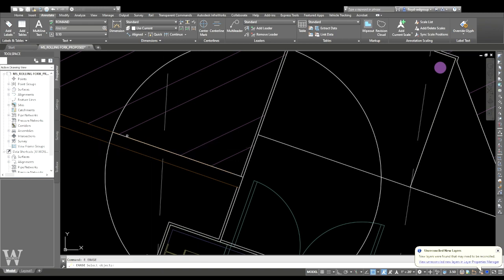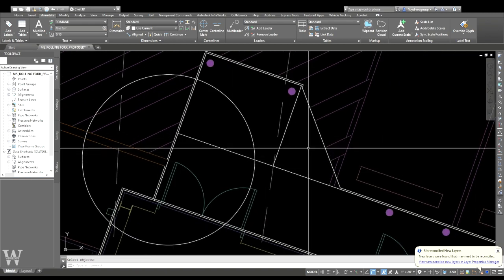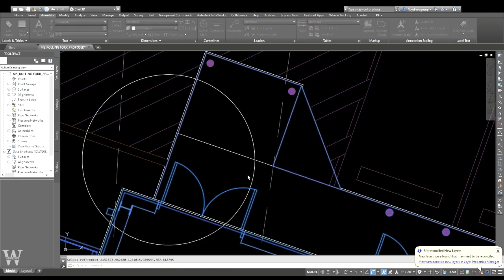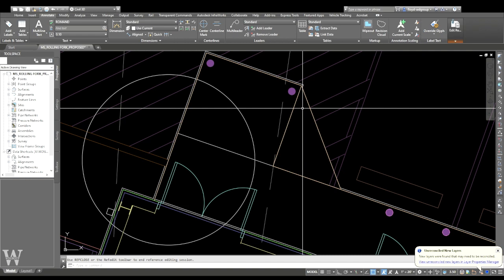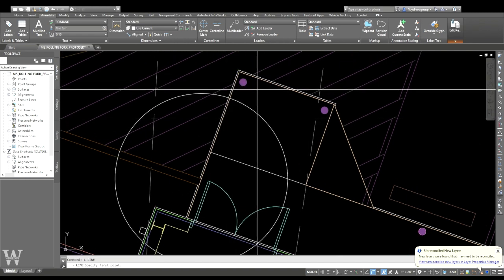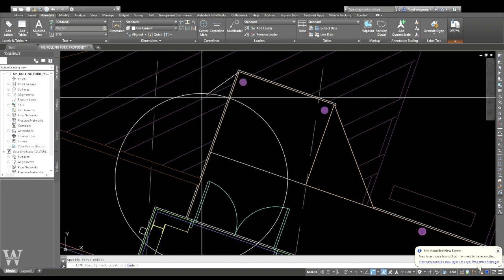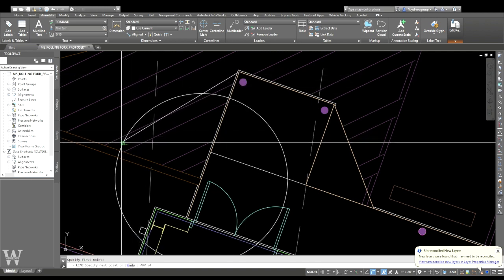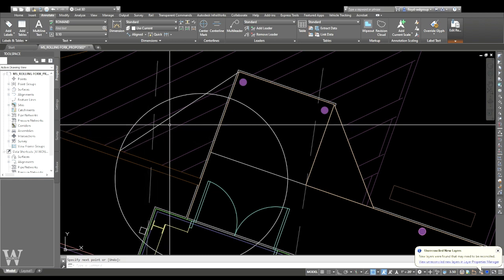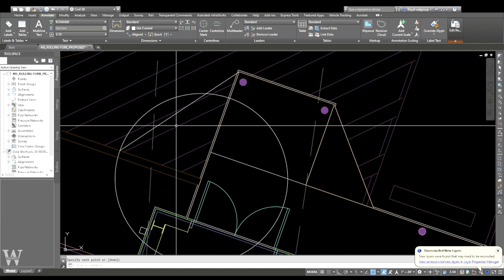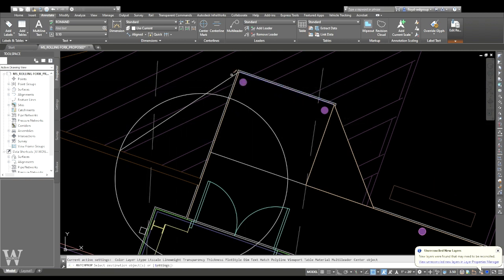And so what I'm going to do is, this is really actually part of my base plan. This little ramp slope right here. So I need to come in here, and what I did is I double clicked on it and opened my X reference up, and I'm going to change my X reference, and I'm going to put that slope right there, and it's 1 to 10 in that direction, which is 5 foot. So I'm going to put that slope right there, and I'm going to match that layer, and I'm going to edit, save changes, and hit OK.